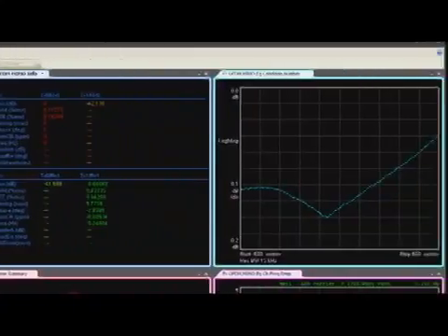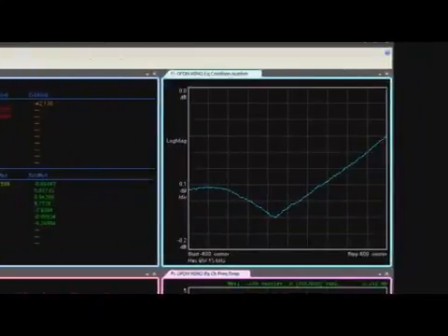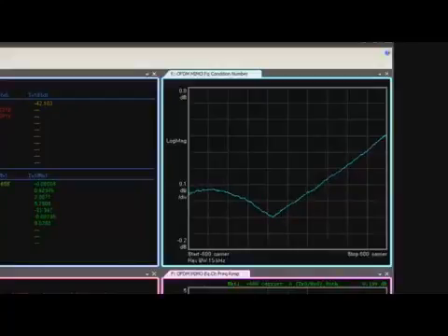The condition number display provides verification that the pre-coding gains are correct and that transmit power levels are properly balanced. For codebook indices other than 0, this determination is not possible through a simple broadband power measurement.